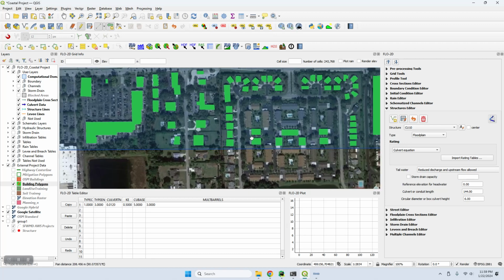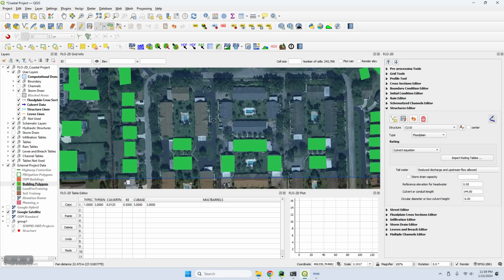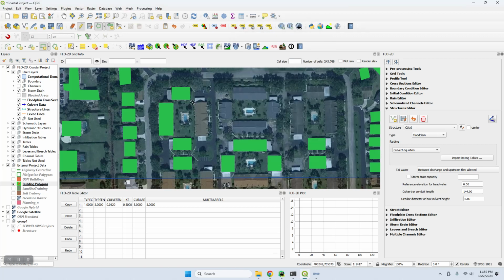Let's go ahead and zoom in on a couple more of these so we can see some different tools. The next tool, we're still on add a polygon, but this time we want to change this to rectangle from extent. And this is very easy. You just pick up one corner with a left click, and then you pick up the second corner with a right click, and then again it's enter or OK. That makes it really fast to digitize these.